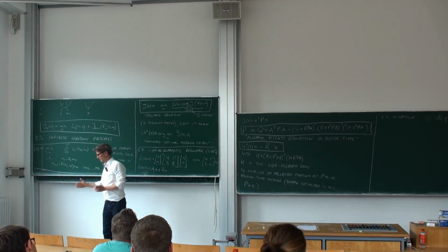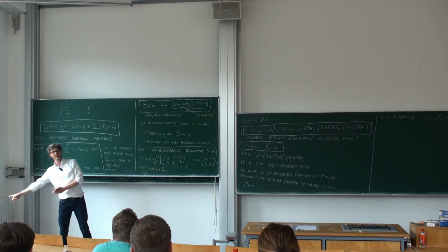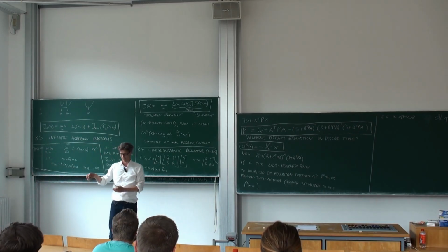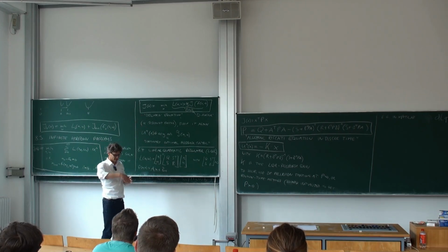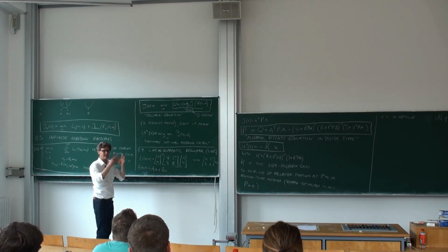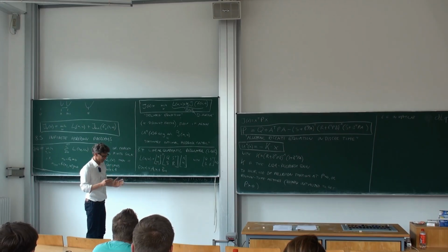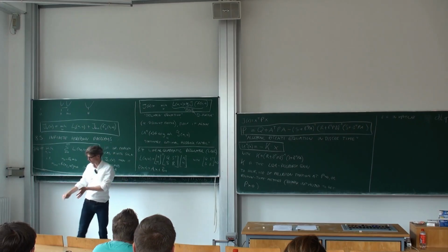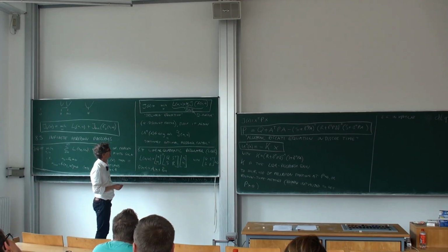Of course, there would be some states, like a speed of 100 kilometers per hour but 1 meter before the wall, that will be an infeasible state. I mean, after a short time, I will have a crash. And so for that state, the cost-to-go function, this J, will be infinity. So there will be a region in state space where the cost-to-go function is actually infinity. It's boring, you don't want to be there. You are anyway doomed when you are there. You cannot do anything. And in the other part of the region, you will still have a cost, and probably it's minimal at the point where you wanted to park, and positive at other locations.